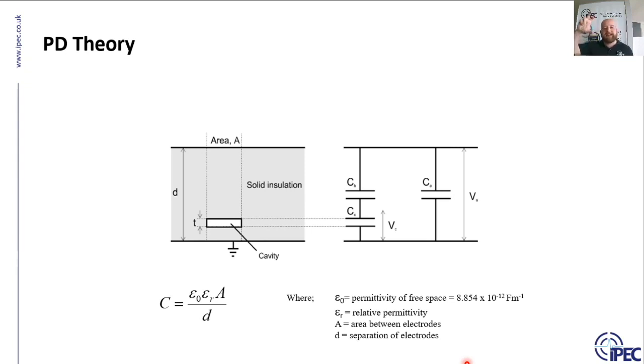It's not because there is gas within the insulation that's causing a lower insulation level. The problem is that the combination of your XLPE or your polymer, your traditional insulation, with a different material, with an air gap, causes an area where you can get an increased point of stress.